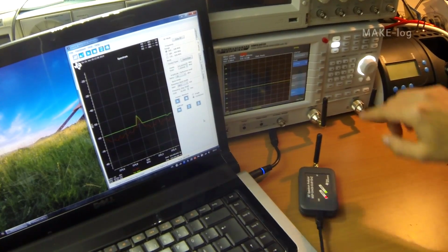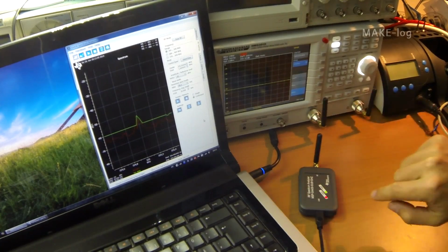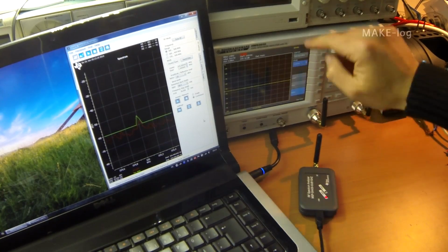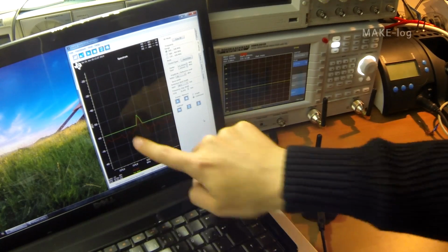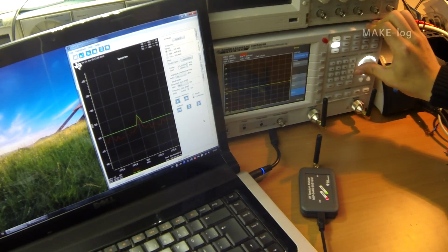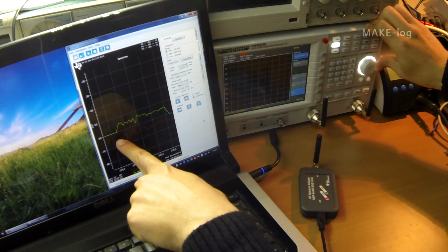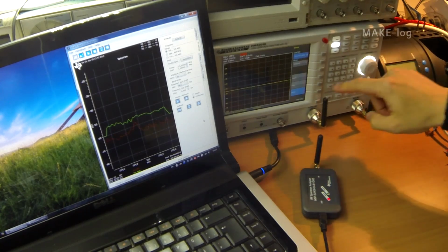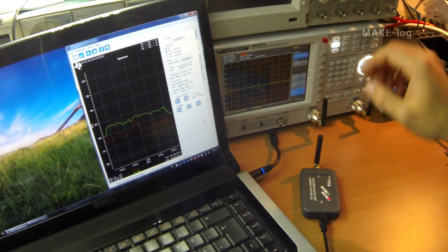For testing the lower frequency range, I have switched the spectrum analyzer's tracking generator to 0 span, so we are outputting a signal at 325 MHz. And we can see it's exactly what the Texas Instruments spectrum analyzer shows us here. I'll change the center frequency and you can see how it is moving. So the frequency which is measured by this spectrum analyzer seems to be quite precise. I must say that the antennas are not optimal for these frequency ranges I have entered here.